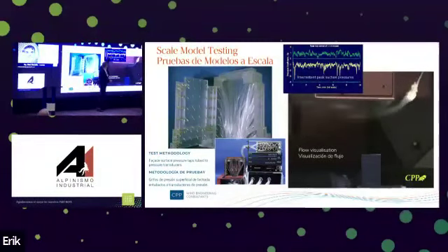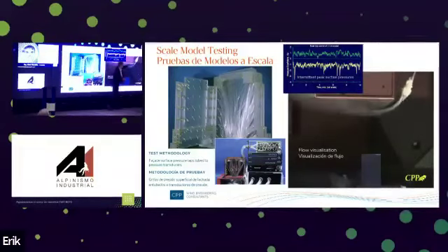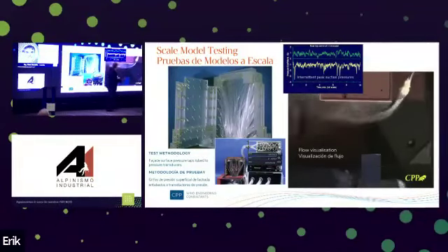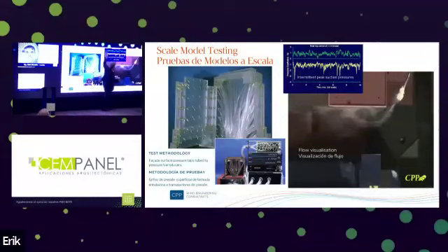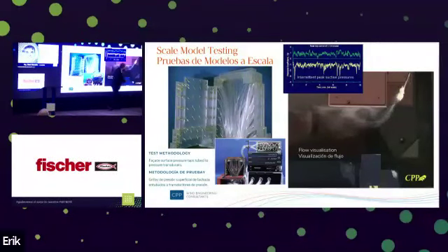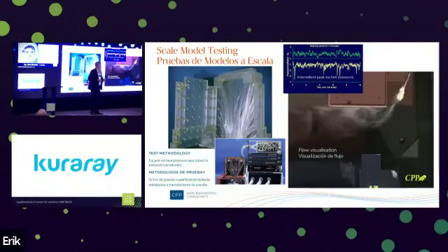This is a time trace of the same time history of pressure at this location. And you can see the highest pressures come from a negative. We get this flow separation, which gives a negative pressure enveloping this point of discontinuity, or downstream of the point of discontinuity. And we can see sometimes we get these like recirculations or local accelerations adjacent to the facade, which give rise to these intermittent peaks, which can't really be predicted without the benefit of wind tunnel testing.